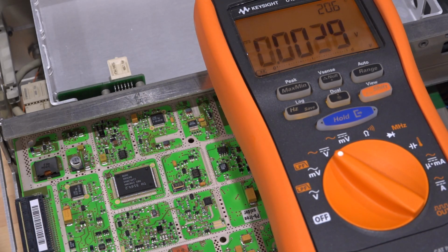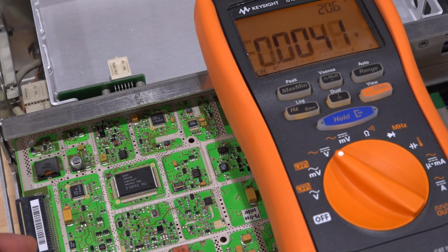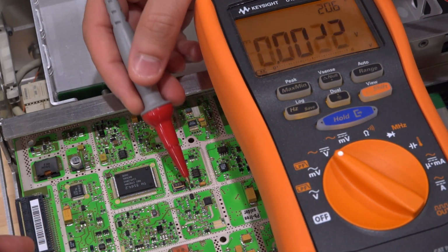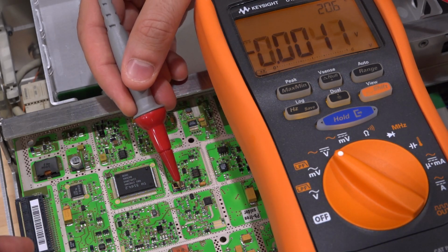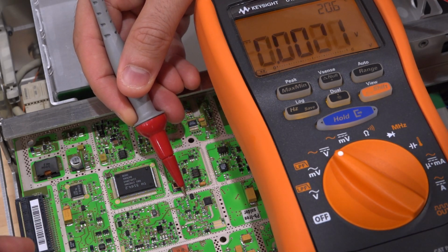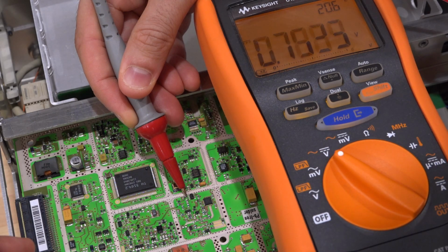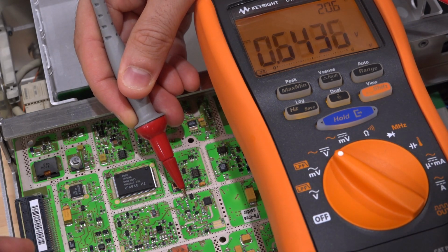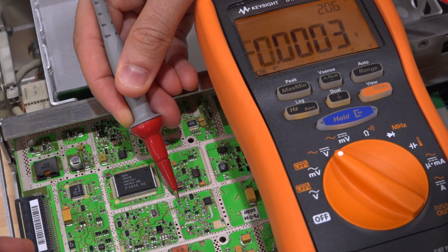So I may have found something really unusual. Hopefully you can see everything at the same time. So I'm going to measure the power supply going on to the divide by 4 circuits. We already measured the power supply of the VCO. That one's okay. So here's the power supply going into the divide by 4 chip. Look at that. 0.7 volts. That's not right.